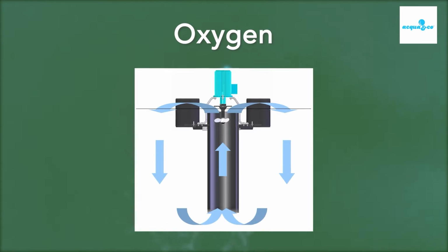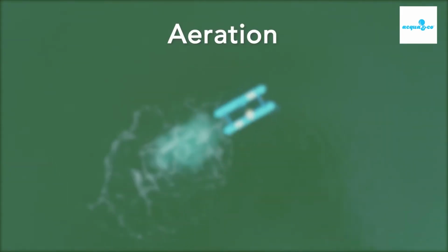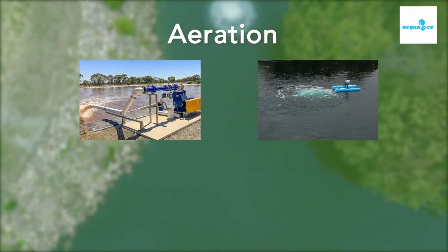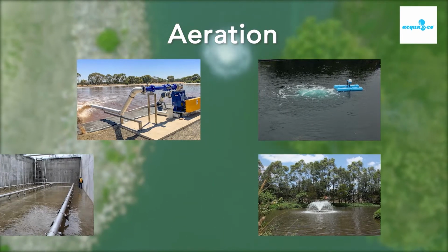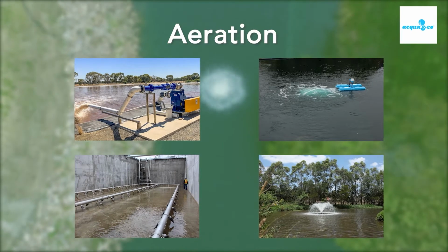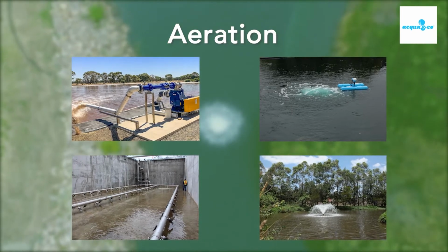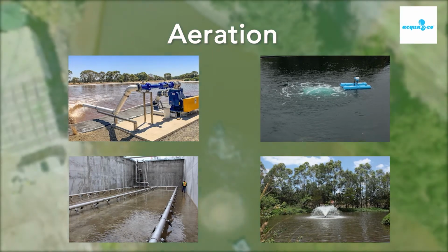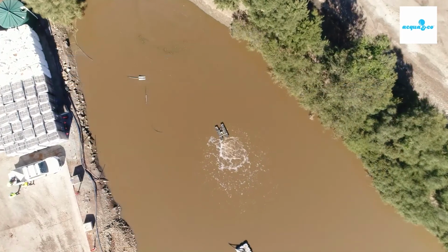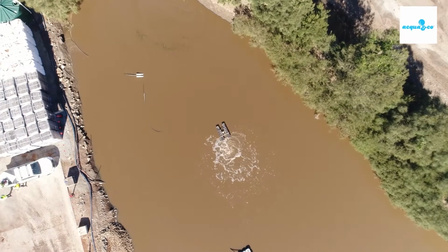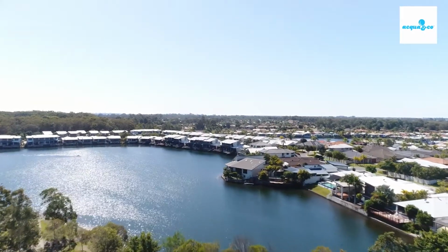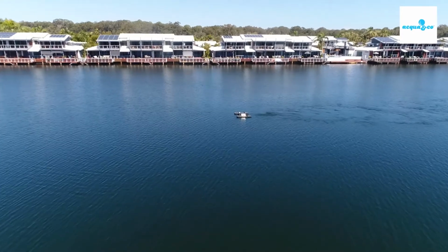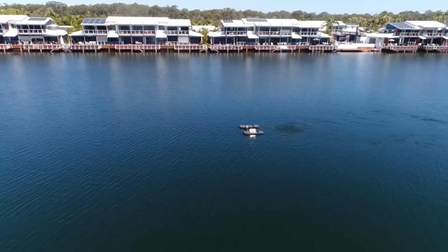Oxygen can be introduced artificially through an aeration device such as a Venturi system, mechanical aspirator, surface aerator, or an air blower and diffuser system. An effective way to introduce oxygen is via a mechanical device that produces a micro bubble and deep horizontal flow. This can help maintain aerobic respiration in the sediments on the pond or dam bottom. When oxygen is introduced to this zone, the anaerobic cycle can be broken, beginning the development of aerobic bacteria populations.